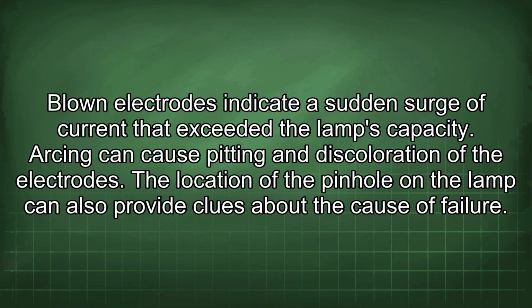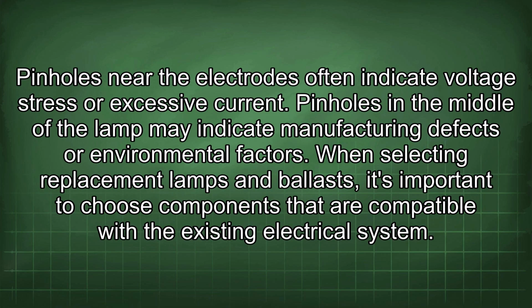Arcing can cause pitting and discoloration of the electrodes. The location of the pinhole on the lamp can also provide clues about the cause of failure. Pinholes near the electrodes often indicate voltage stress or excessive current.